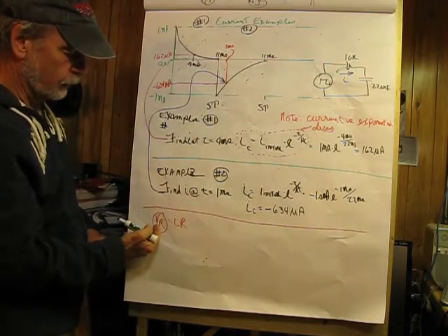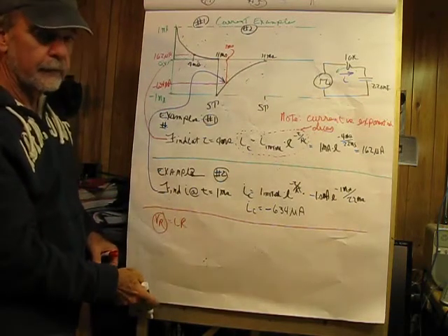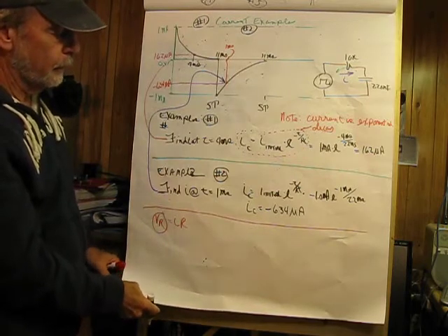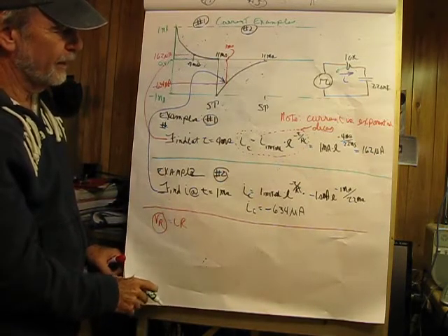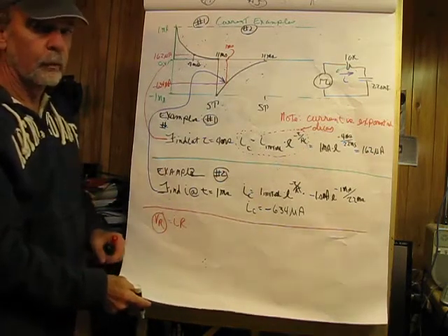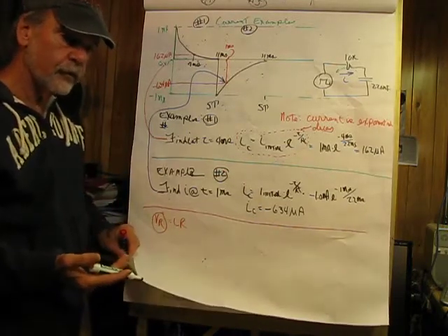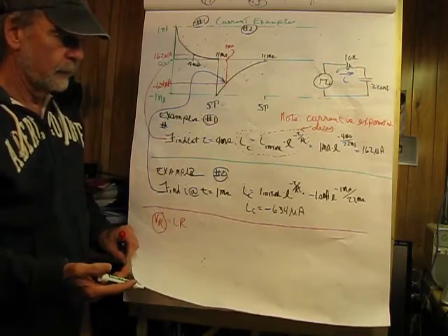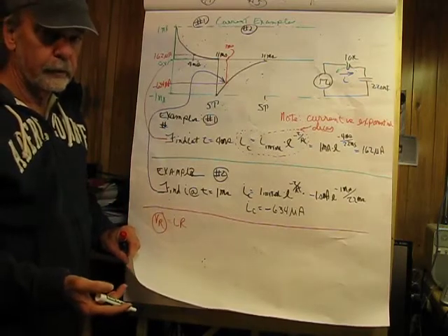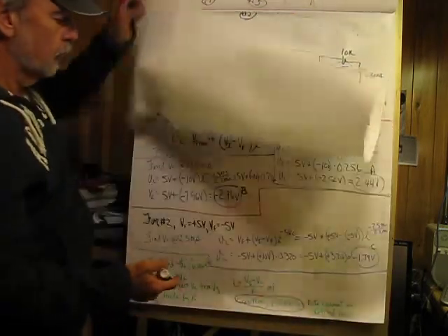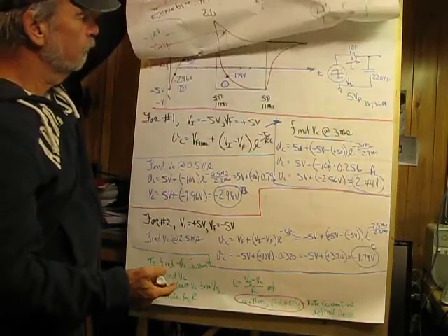So the voltage across the resistor is basically I times R. And as you can see here, if you understand the waveforms and when to use the charging waveform and when to use the discharging waveform, a problem decomposes basically into Ohm's law. So that's the hardest part of this.